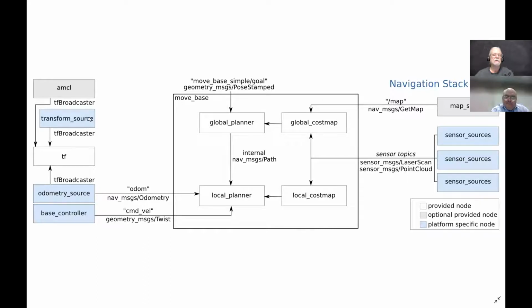I think that's what that's telling you here. And again, you can create that by putting command line static transform publishers into your launch file. So you can say, here's my base link, here's my base footprint, here's the difference between those two, and that generates that for you. And then you can create another one that says, this is the transform between base link and GPS. And then you put all the numbers in there, and that creates your next one.